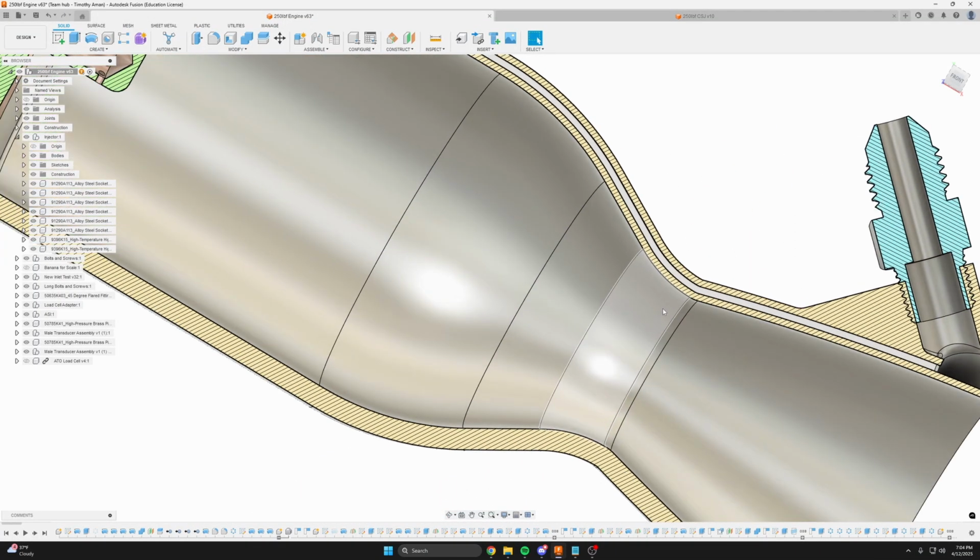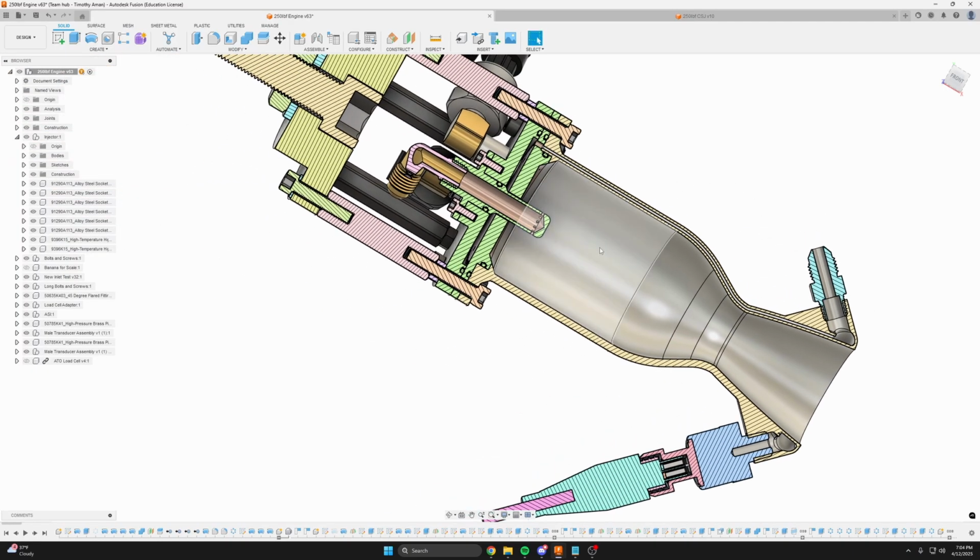and look at the material properties. For example, this is printed in aluminum, an alloy called AlSi10Mg. So find a table. I'll link one for AlSi10Mg, but whatever you're printing it in or whatever material you're making your chamber out of, you have to look at the material properties.